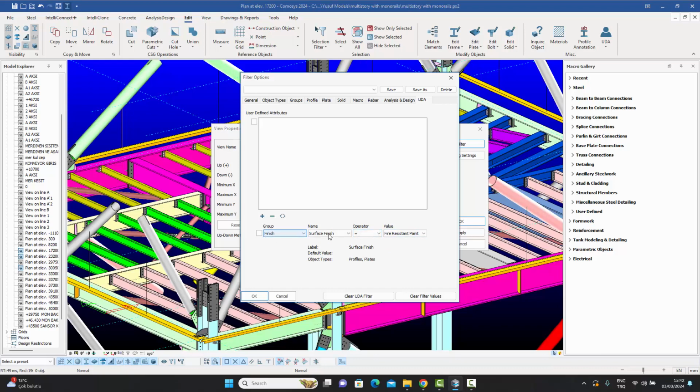And once I've created this filter, let me press this plus button, and I can add it over here to the top. Basically, whatever I add to the top, those will be the filters which I can then use for my filtering. Let me create another one. Use the erection contractor, the other one which I created, which I didn't show you, but I have assigned it to certain beams.